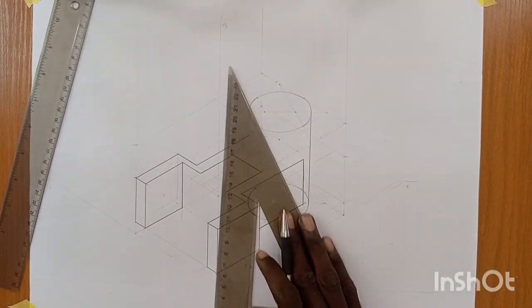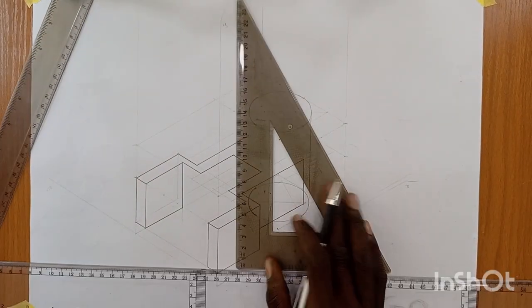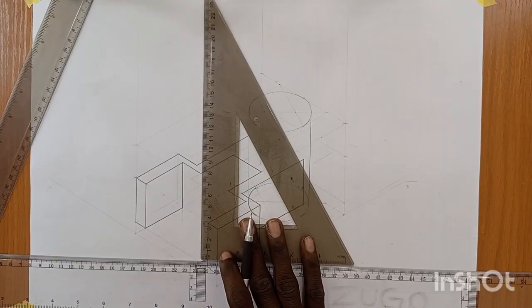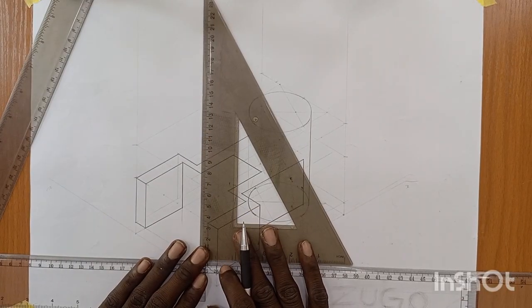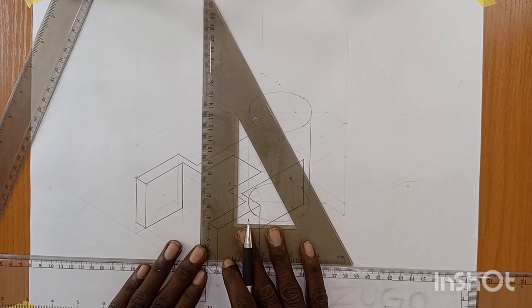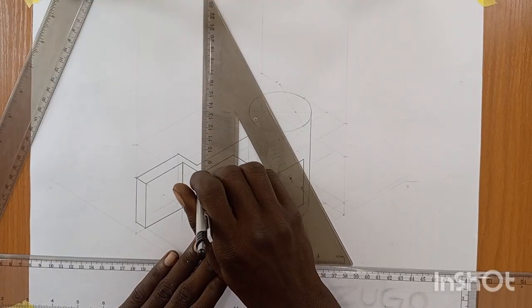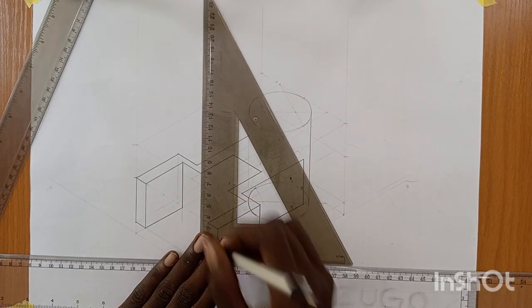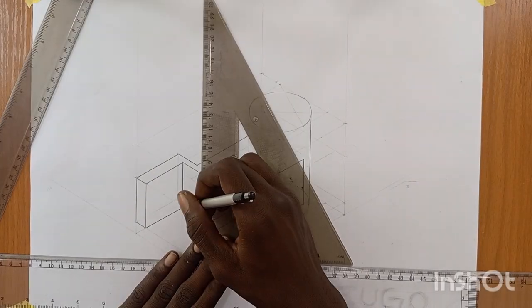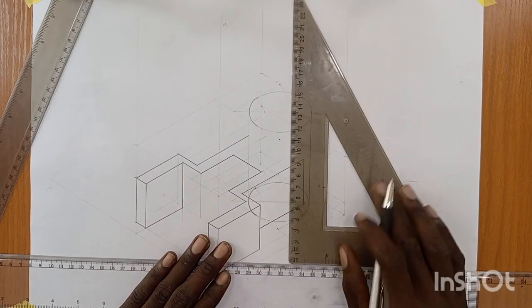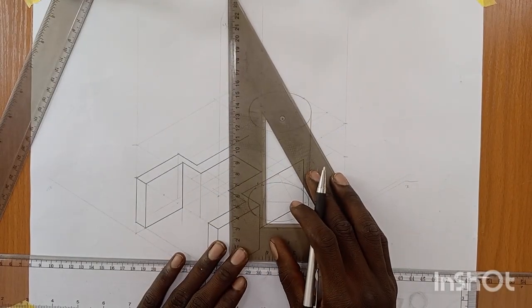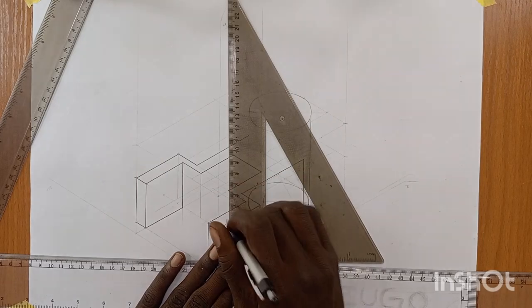We're going to measure just using your 30-60. This is very, very important in isometric drawing. 30-60. As you can see, we haven't used 45-90 yet, because it is not needed here. The 30-60 is very vital here. So now let's take it downward. I'm going to measure this length here, it is 40. Since you have a parallel line here passing here, this is going to be 40. But let's leave it and measure it to confirm. So this line here should be 40 downward.